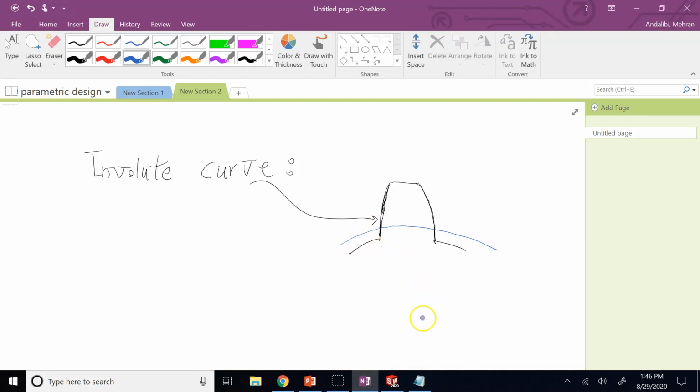What circle is this in a gear? That's the circle I mentioned earlier in this lecture. It's called the base circle. So base circle, for which the radius r of base is r of the pitch circle times cosine of the pressure angle.